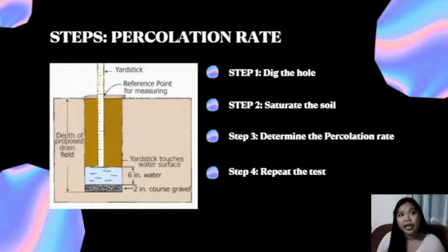Interpreting the result of your percolation test: if your average VP number is between 15 and 100, then that's right, you can have your soakaway. A minimum value of 15 ensures that your soil's percolation rate is slow enough to allow the influent to be sufficiently treated before reaching the groundwater.